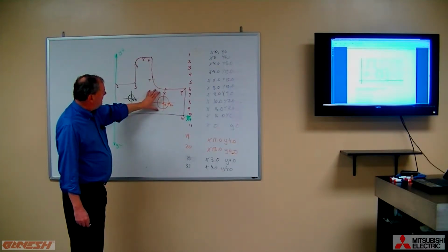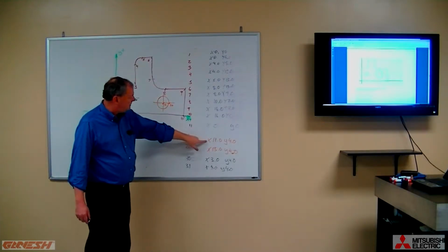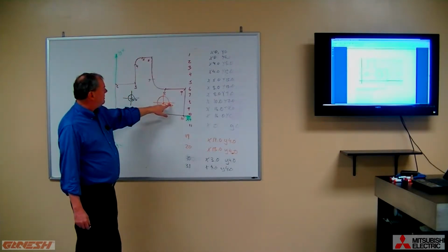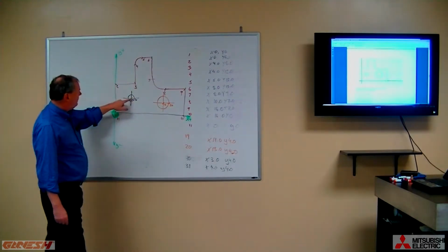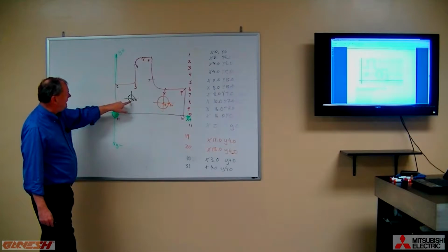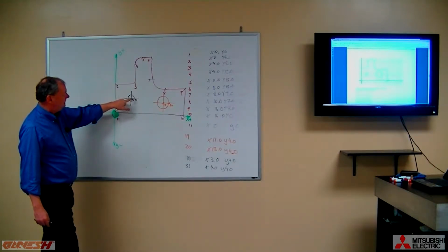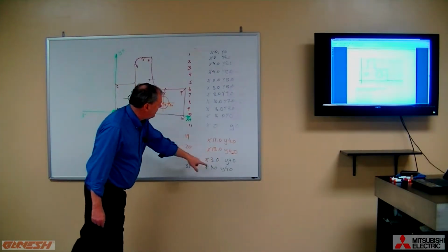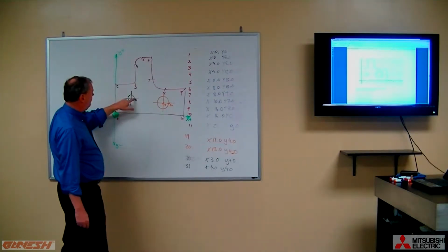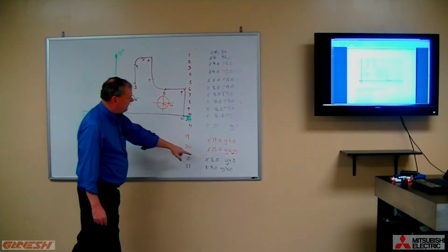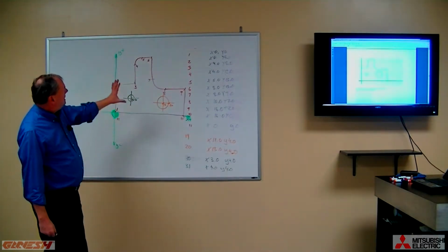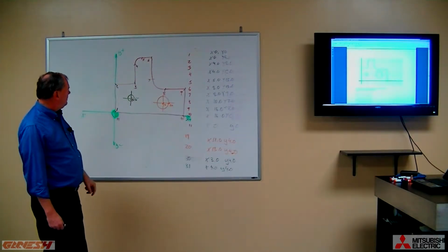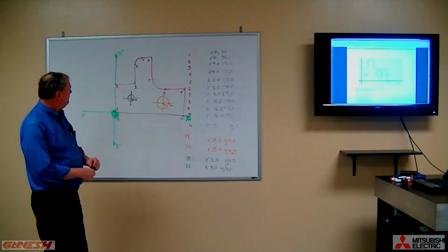I've also taken these circles and identified an x location for the center point and an x location for the point out on the periphery. So we've got two more points here. The black hole has a point at the center at x3 and a point out on the periphery where the center line crosses the feature at y4. So now, given this, we have enough information to create a pretty nice part program.